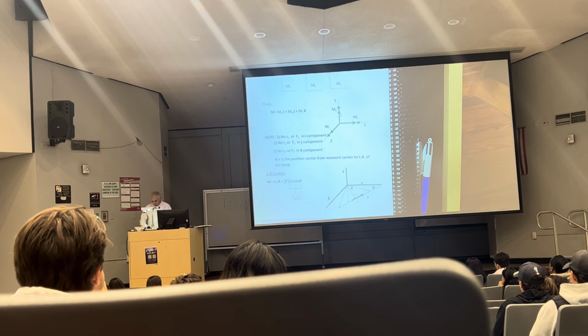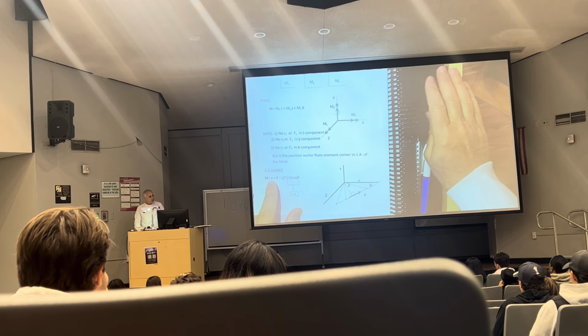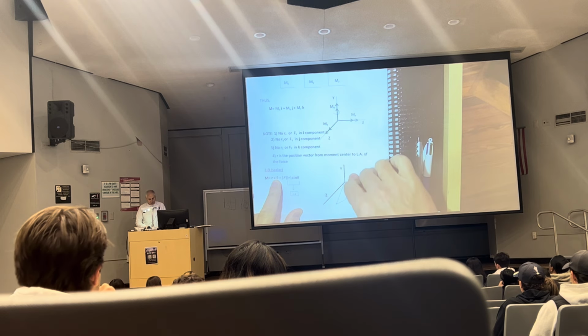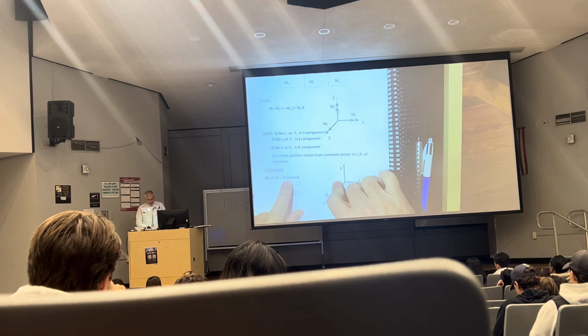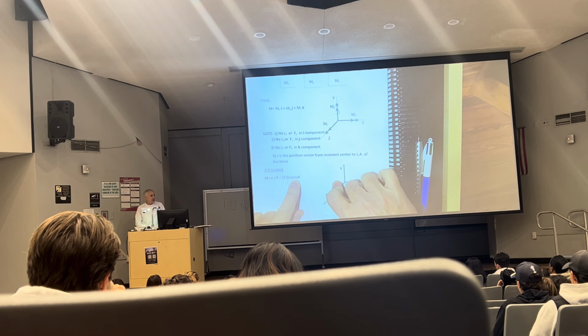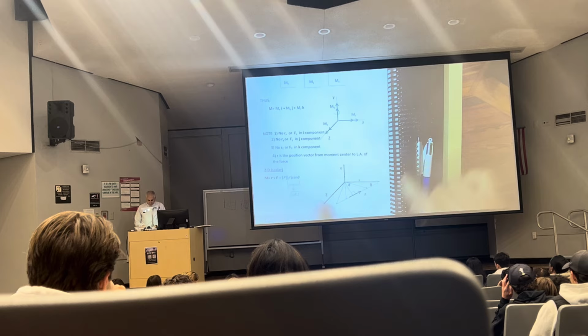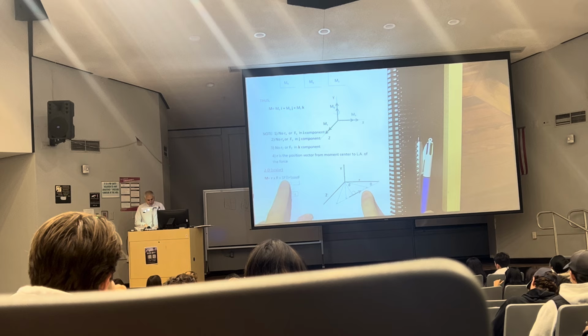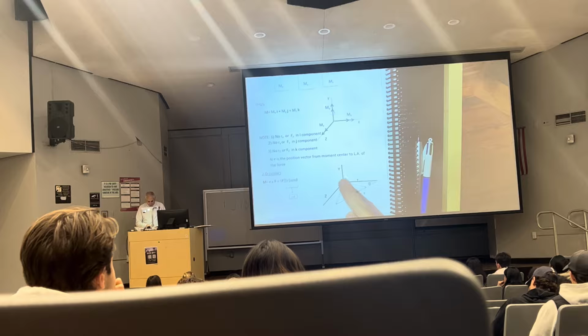Whatever this x value is from here to here, I would know. So if you look, here's the equation. R cross F. By definition, we saw this in the vector algebra. It's equal to F times R times the sine of the angle in between. Well, there's the angle in between the R and the F. If I were to do the perpendicular distance, this would form a right triangle.